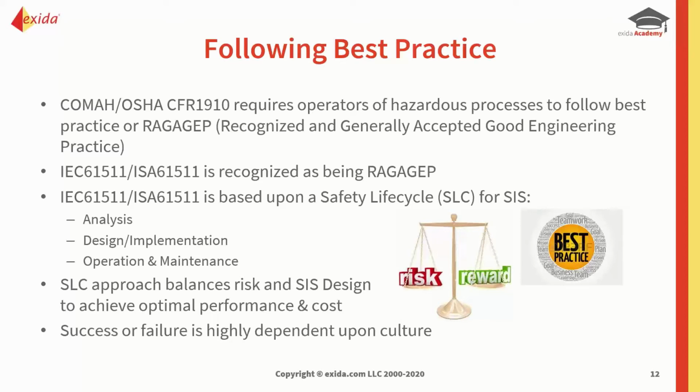So the whole purpose of this is to help us balance our design against the risk so we can achieve optimal performance and cost. In other words, we don't want to have an over-designed system, and conversely, we don't want to have a dangerously under-designed one in terms of the number of safety instrumented functions we need in the safety instrumented system and what those target safety integrity levels are for those SIFs. The other thing, of course, is that it is highly dependent upon the culture of the company.